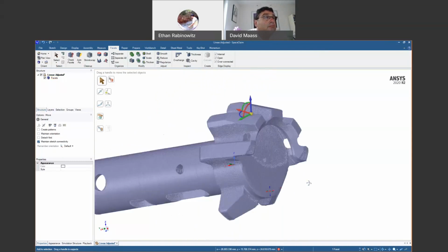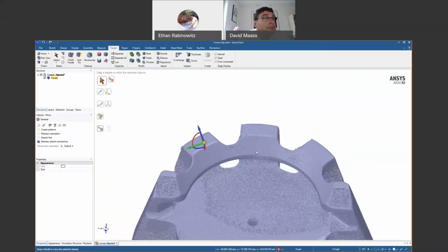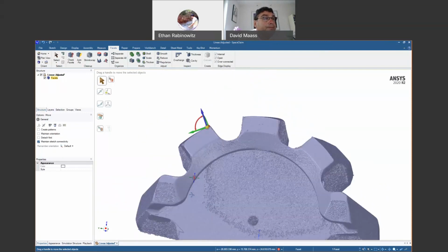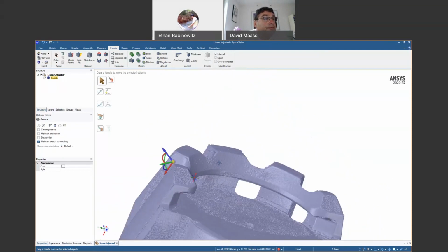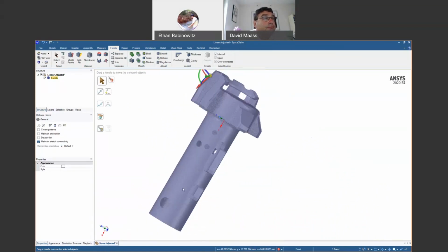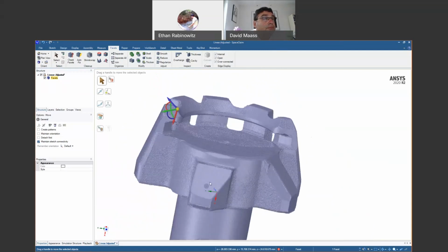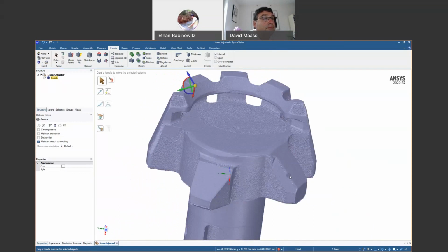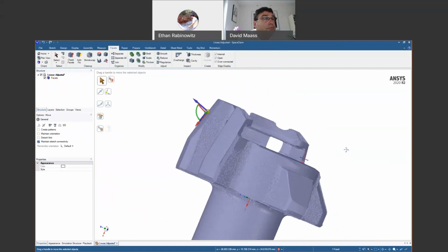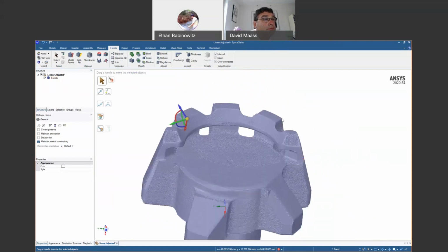So what I'm thinking, what is similar between them appears to be this conical chamfer here. Right. So what I'm thinking would probably make the most sense is to revolve, say, this pin, just the common part of the head here, and then we can come in and add the tabs semi-individually, just because there's definitely some similarities, but definitely some differences there. So, all right, let's do that.